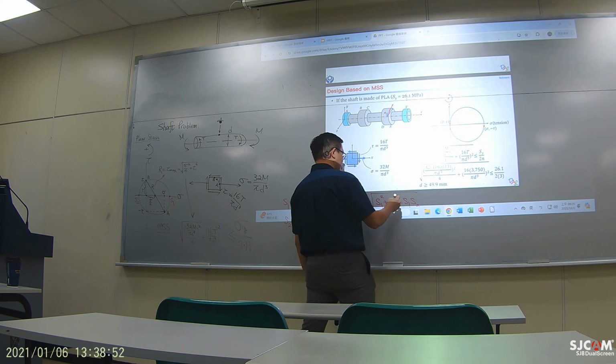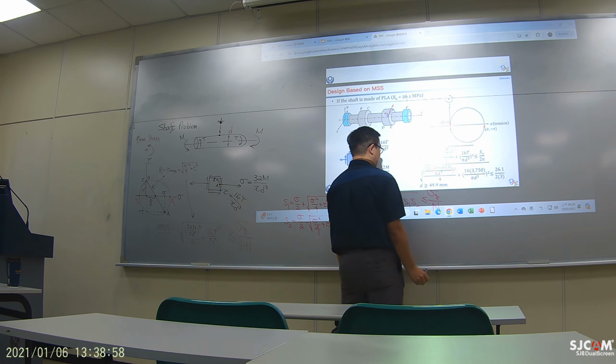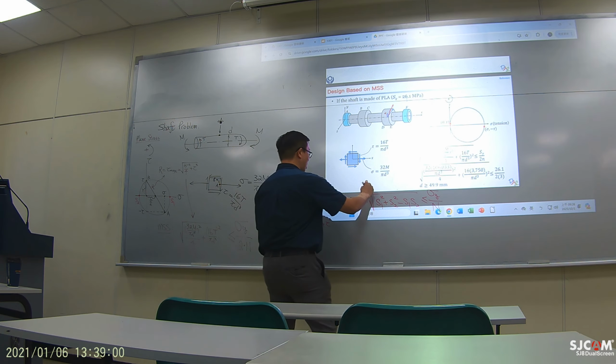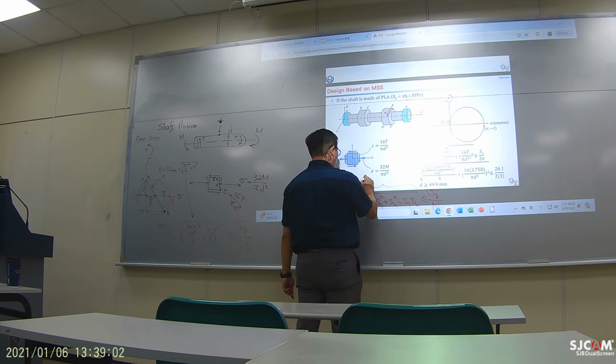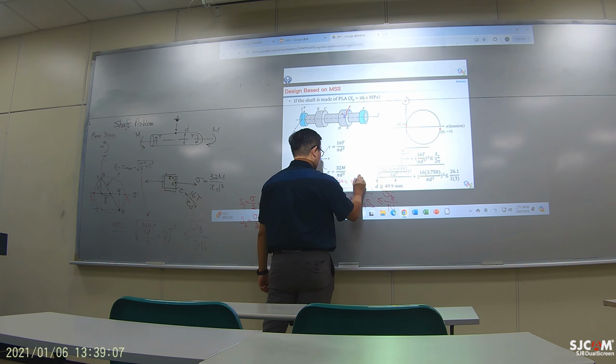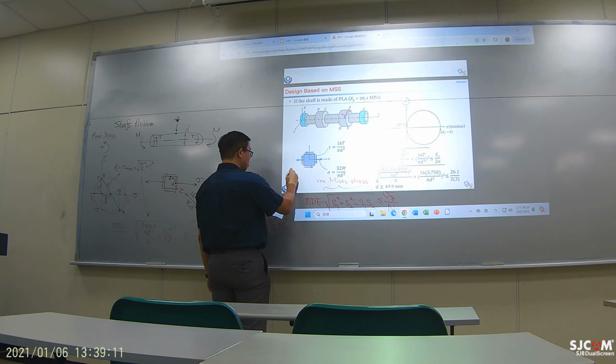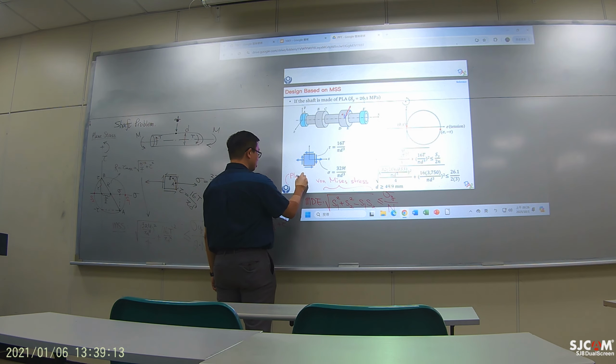And that value has to be smaller than the yield strength over the safety factor. Right? This guy is the von Mises stress. So for plane stress problems.